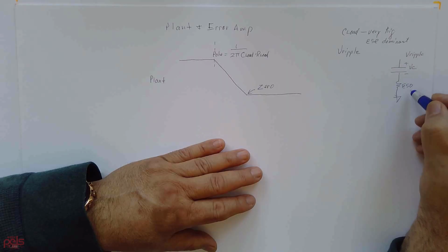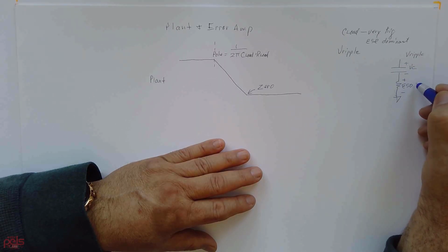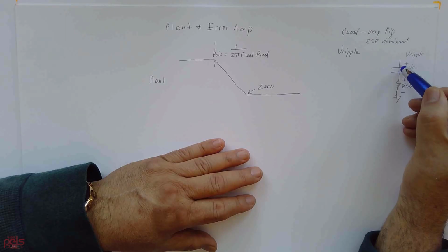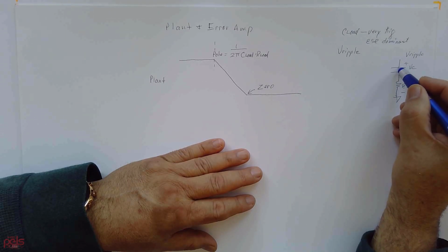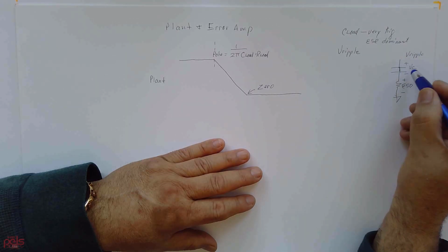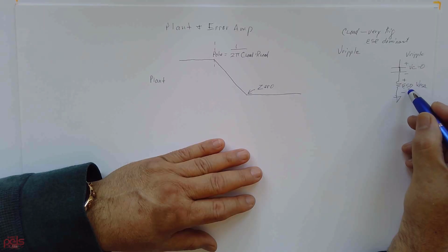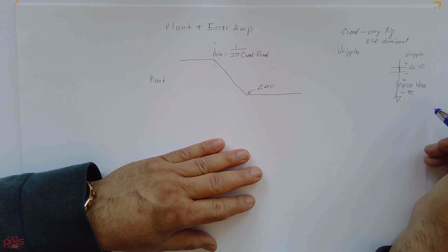and this voltage, which is the ESR. If you make the capacitor very big, you can think of it as a short. If it's a short, then this voltage goes to zero, and your ripple will be dominated by your ESR.